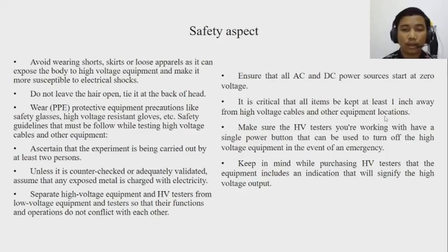Make sure the HV tester being worked with has a single power button that can be used to turn off the high voltage in the event of an emergency. Keep in mind while purchasing an HV tester that the equipment includes an indication that will signify the high voltage output.